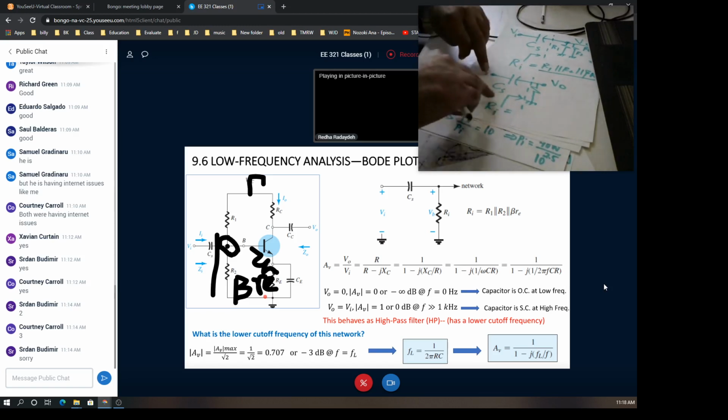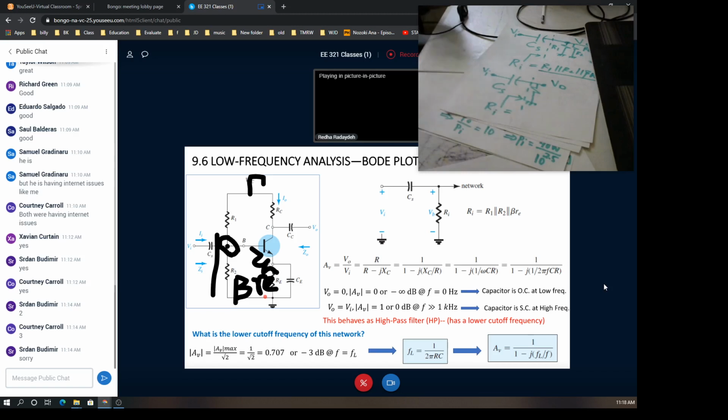Now the procedure we are doing will be repeated for the other two capacitors. Same procedure. When you consider the effect of CS, we short circuit the other two capacitors. We neglect them, like a superposition principle. So first we consider the effect of this capacitor; these two will be short circuit.